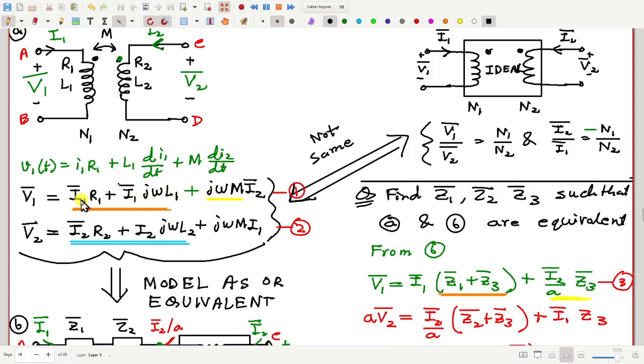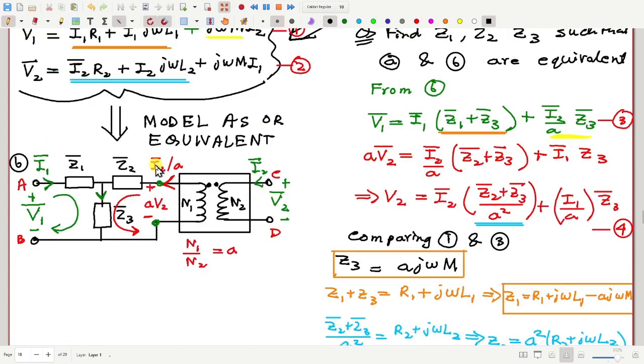So many non-idealities like non-infinite permeability and non-zero coil resistance are modeled in these two equations. But there are many more things which are still not modeled in these equations. One among those missing things is eddy current. While writing these equations, eddy current is not considered anywhere.